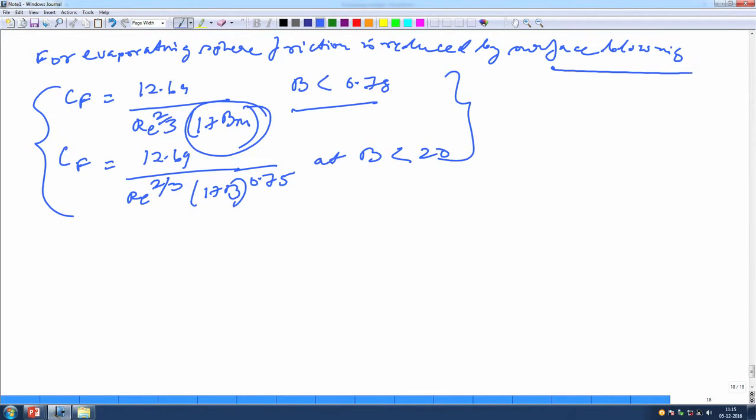So, this particular part is quite obvious. Now, the skin friction coefficient is actually reduced because of the surface blowing, because of the thickening of the boundary layer, right. This will in turn reduce your Us, that means the surface velocity that you are going to generate inside the liquid phase. Now that we have analyzed everything, you know Us and everything, the transient heat transfer can now be solved.